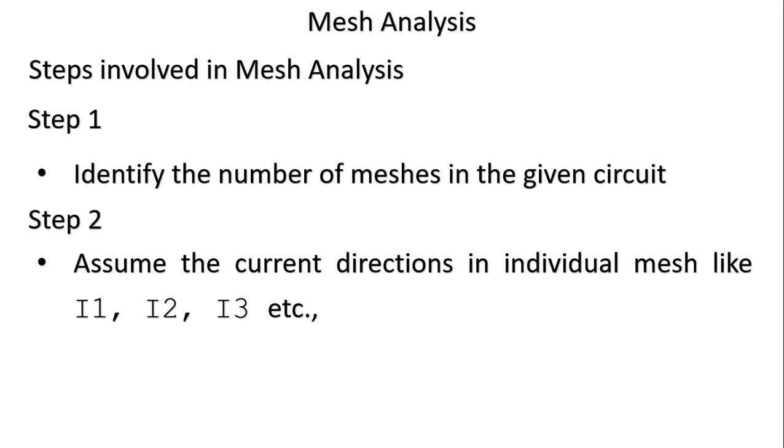Coming to the next one, there are certain steps involved in the mesh analysis technique. First, we have to identify the number of meshes in the given circuit, and then we have to assume the current components in various meshes, like I1 in the first mesh, I2 in the second mesh, I3 in the third mesh, and so on.